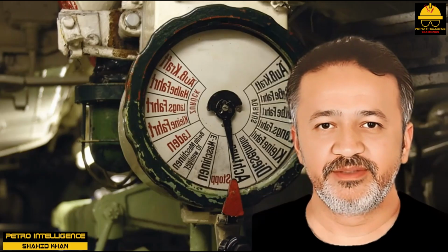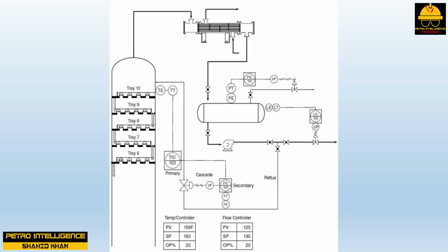Cascaded control. Cascade control uses elements from 2 separate control loops. One of the controllers functions as the primary controller, and the other functions as the secondary controller. This relationship is often referred to as master-slave control. This picture illustrates the basic elements of a cascaded system. It is important to point out that in this type of process control, controllers will communicate only with other controllers.